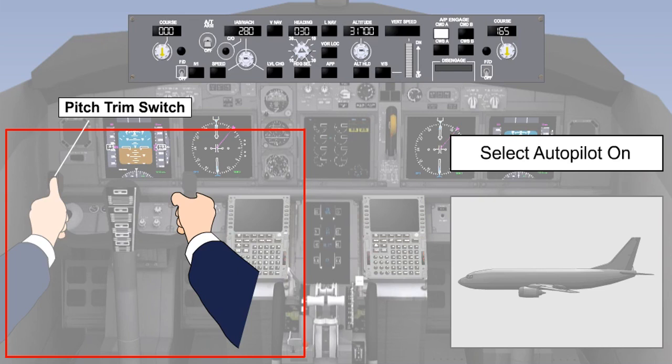Most airliners have a trimmable horizontal stabilizer and elevator combination for pitch trim and control. If the auto-trim system fails, the autopilot will not remain engaged. It cannot be allowed to control the aircraft if it cannot trim in pitch. If the pilot operates the manual pitch trim when the autopilot is engaged, the autopilot will disengage.